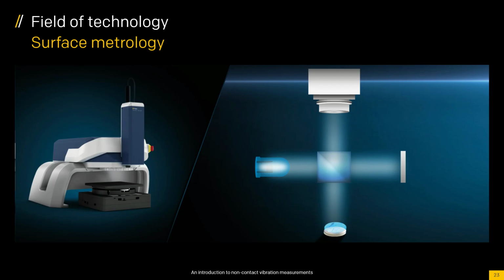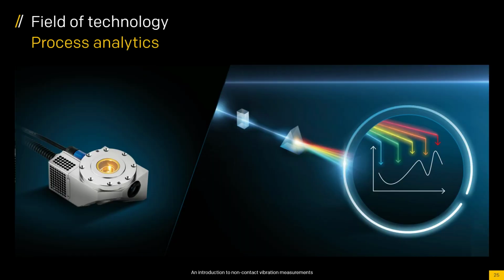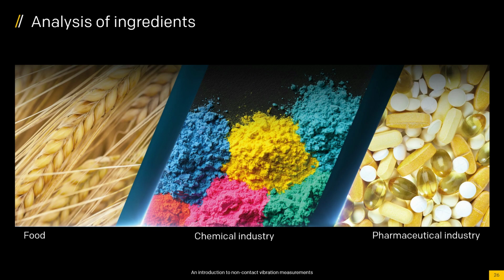So for example, number one, we can do a background measurement, just like how you would do if you're doing a microphone SPL measurement. You can also mount a contact transducer on the back of a vibrometer and normalize your data. We have done that, honestly, not that many times in my 20 years, but maybe a couple of times, mounting an accelerometer, some kind of contact sensor on the back of the vibrometer, and then measuring that, and then removing the movement of the vibrometer from the data.